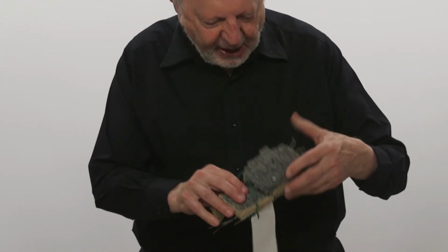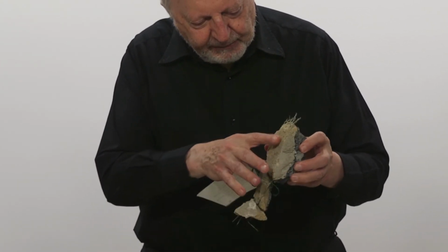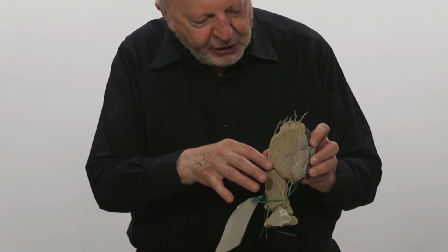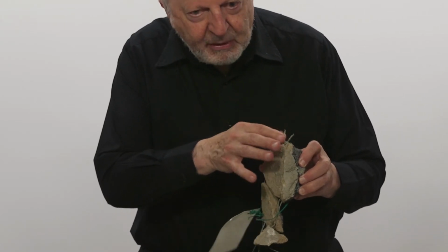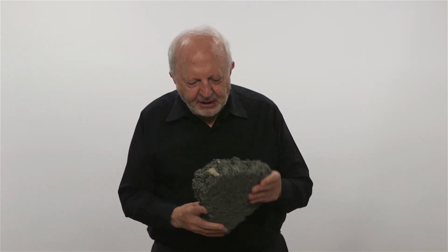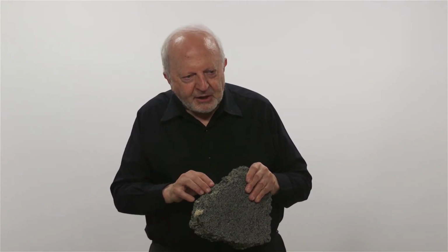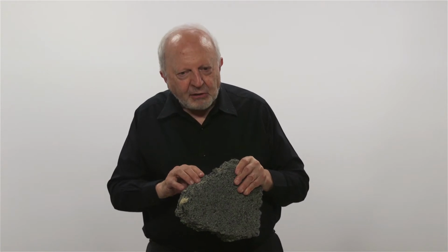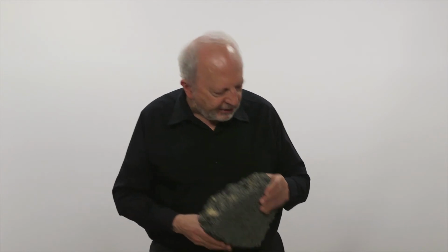And here's an example. This came from a building which had concrete bricks, and then on the face of it rendered again to look like a stone finish, but in this case with a reinforcement of wire mesh to hold the rendering on tightly. This coke breeze material was also used for reinforced concrete, but not for very long. The reason is that coke breeze, the product of gas making, contains a lot of sulphur waste in it, and the sulphur tends to corrode the reinforcement. So it's not good for reinforced concrete, but quite good for mass ordinary concrete.